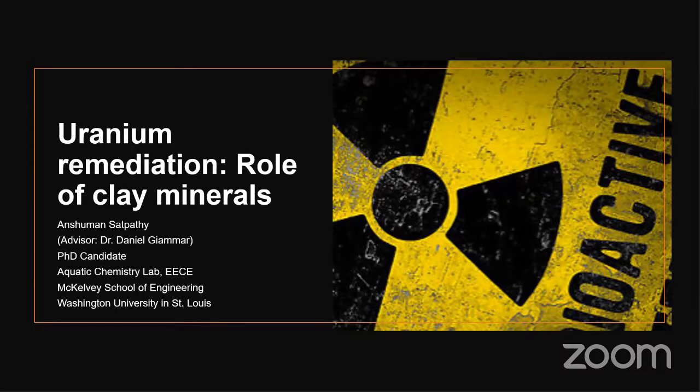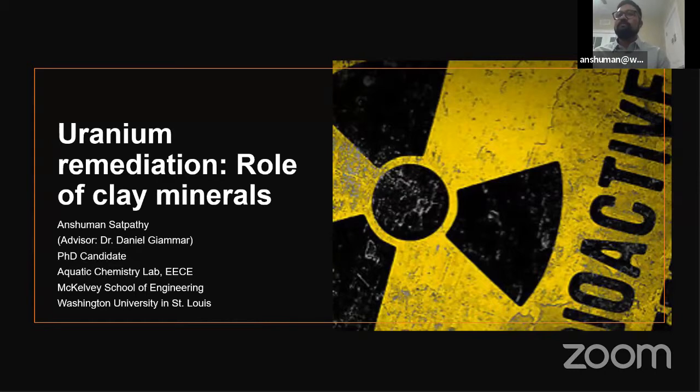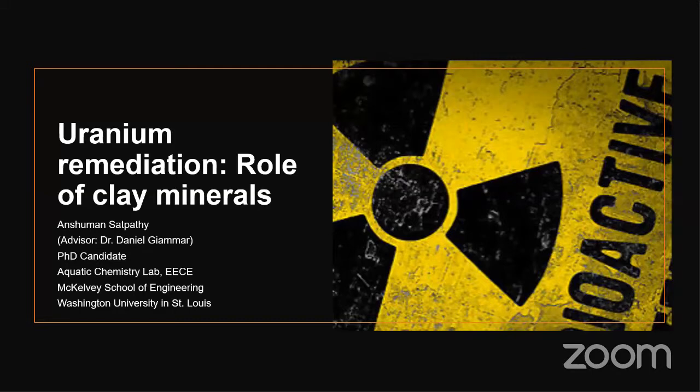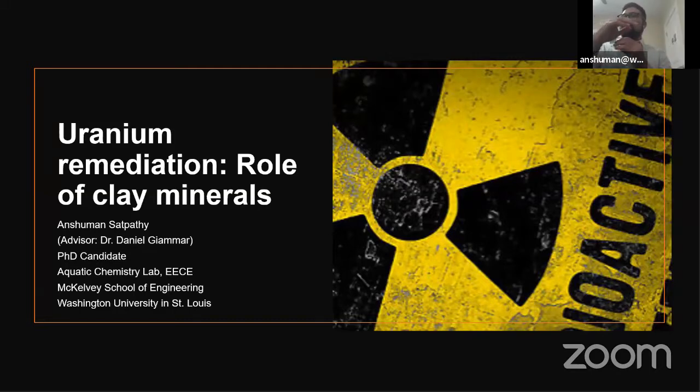Next question, please. What is the interaction between sodium loading and uranium reduction? Okay, so I did not mention that in detail here, keeping in mind the format of today's session. Sodium actually suppresses the cation exchange sites. Clay has a flaky structure, so there are interlayers within the clay. The interlayers have a lot of sites where the cation can directly exchange. These are occupied by sodium.